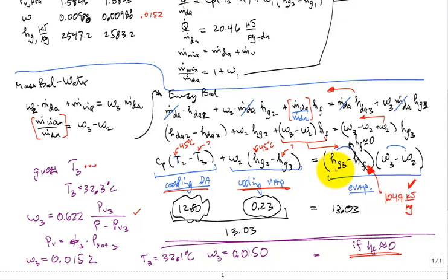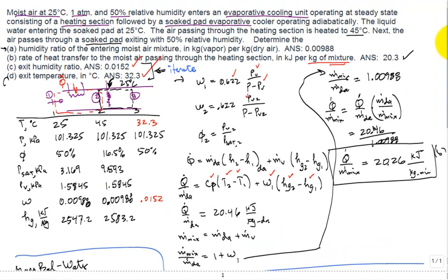And then what about the h_g, we'll go back and say it's leaving at 32.3 degrees C. Well, that is 2,560.37. So something around 2,560 versus 105. So that's why this can be neglected. Okay, well with that, we're done with this problem, and hopefully that was helpful.